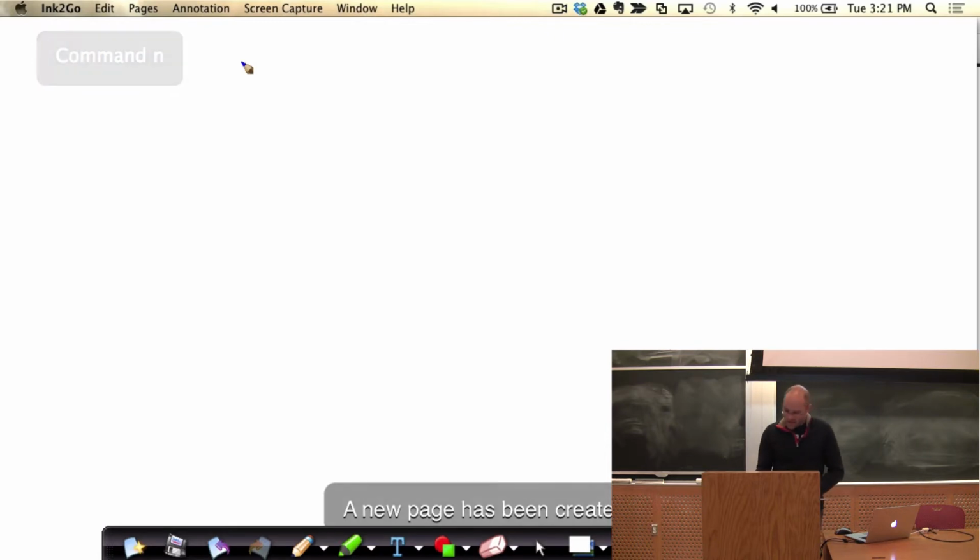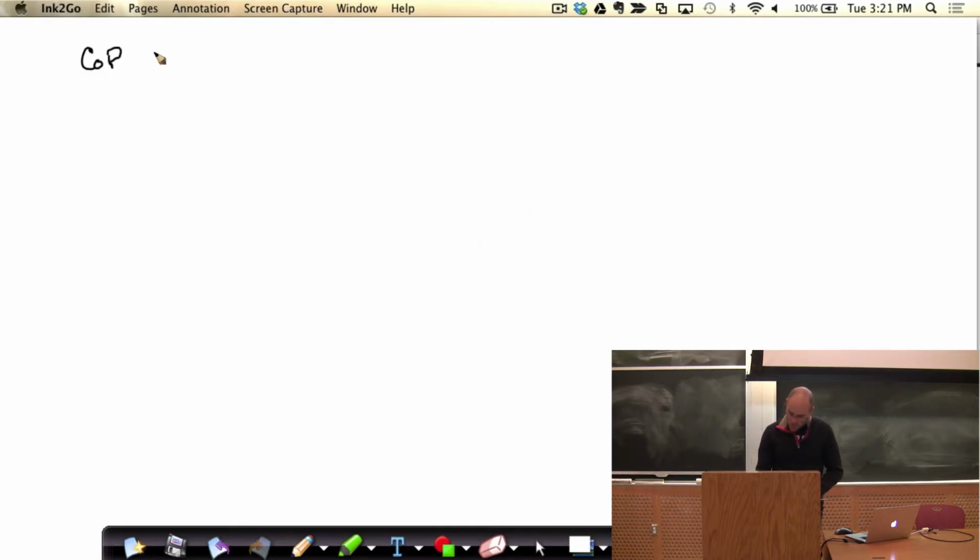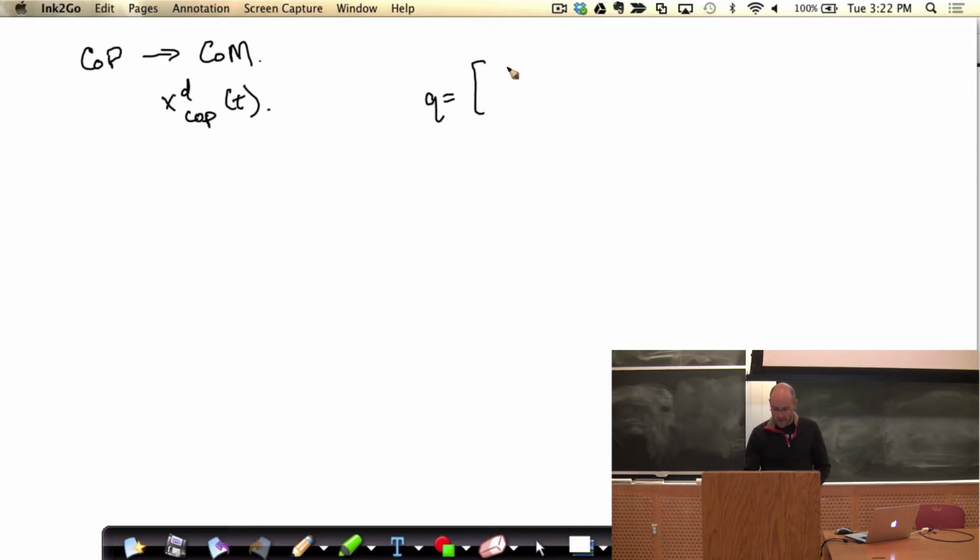Right, so let's think about my mapping from center of pressure trajectory to center of mass trajectory. Okay, so I'm coming in with a desired center of pressure over time. Let's make a planning problem where Q is, I'll do it in 3D here, even though I've drawn everything in the plane so far, because it's easy to do in 3D.